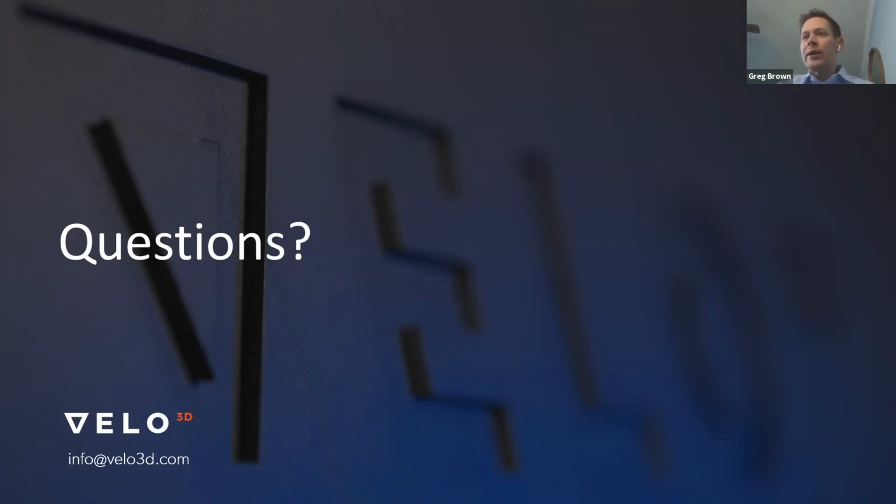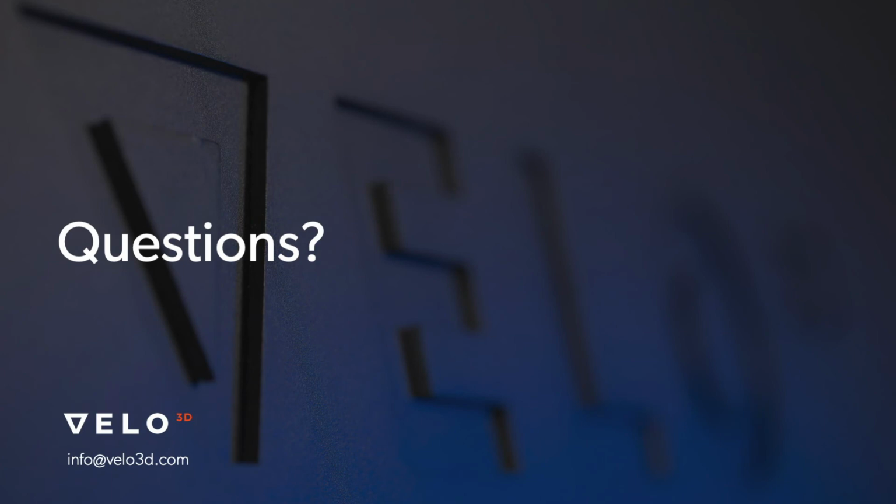So the way it works right now for the skin detection algorithm, at least, is that at a particular region on the part, it ends up outputting an XY coordinate in a layer position, and then a flag, basically 0 or 1, as to whether or not we expect that there's a defect or whether we think it's okay. And then you can export that if you want as a large table, basically, to identify where on the part you expect the defects to be. But it's distilled down from the raw data, so you're not getting the super high frequency sampled data in that case. You're just getting something more manageable, which is XYZ location and whether or not there is or is not a defect.